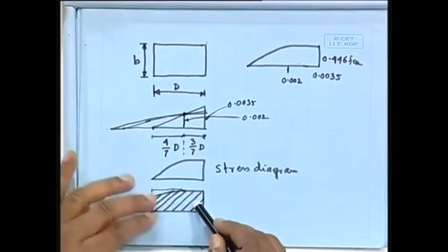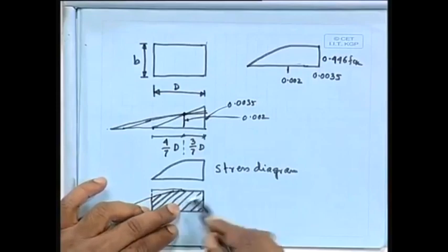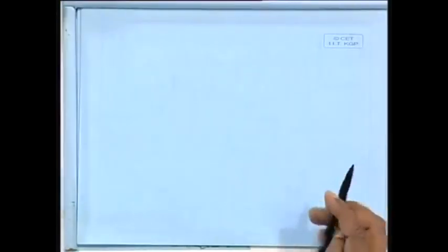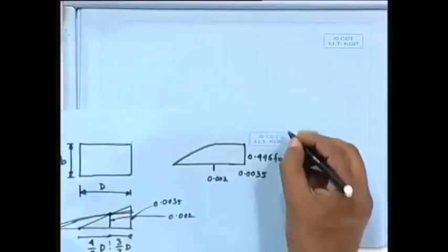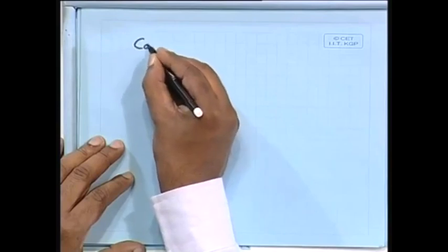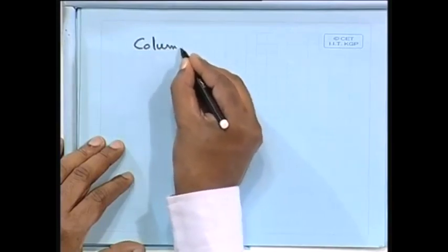And then we can plot it, and that is called the interaction diagram. So it is not possible directly the way we have computed so far, the deterministic way. Here we can say it is a little bit iterative. What you have to do, you have to draw the column interaction diagram.